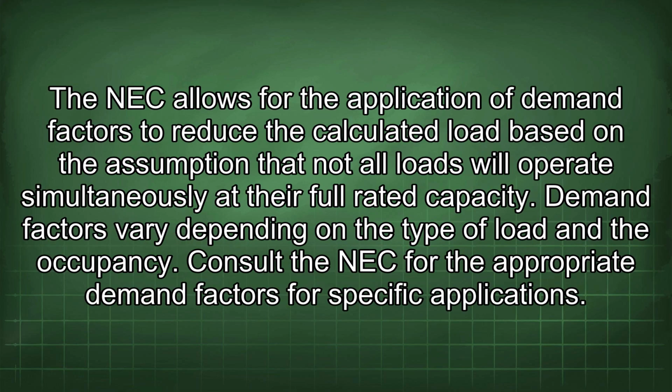The NEC allows for the application of demand factors to reduce the calculated load based on the assumption that not all loads will operate simultaneously at their full rated capacity. Demand factors vary depending on the type of load and the occupancy. Consult the NEC for the appropriate demand factors for specific applications.